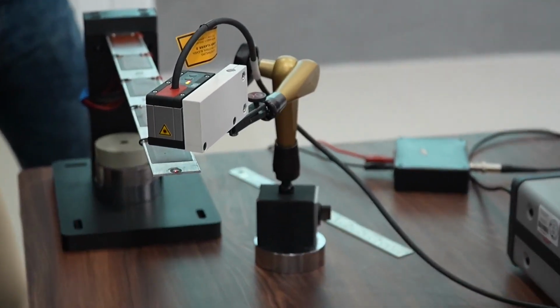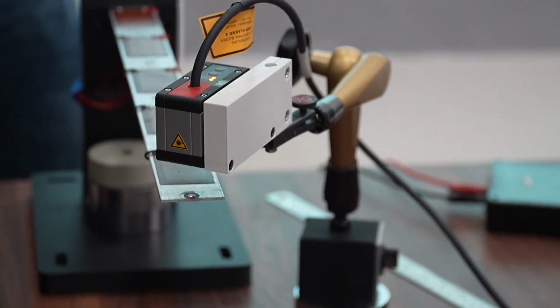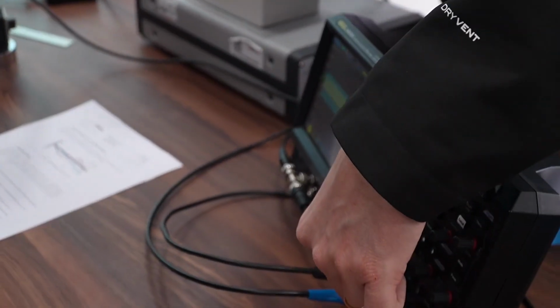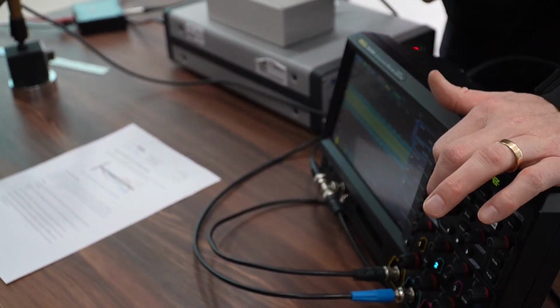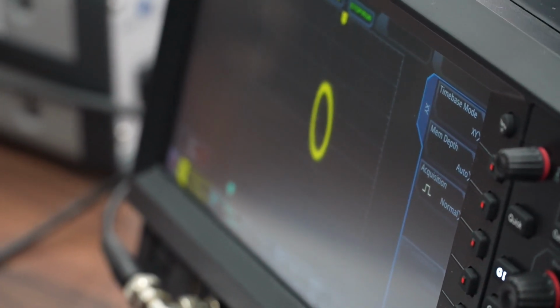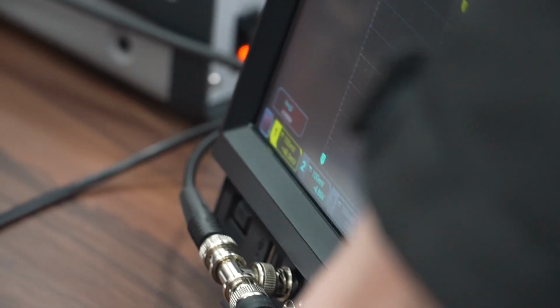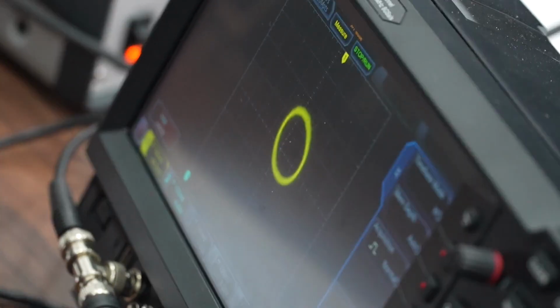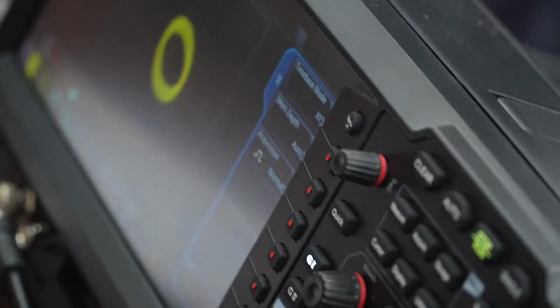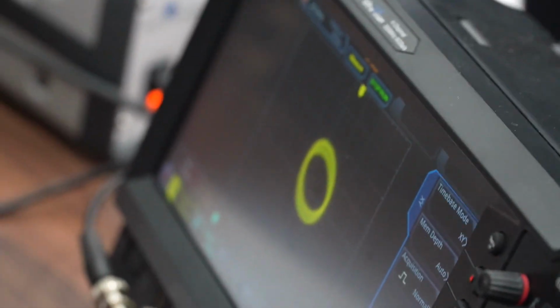So can we put that up a little bit? Up a little bit. Up a little bit. Okay, something like here. Okay, and if we now go again to the XY plot, let's see. It's not a perfect circle because we can zoom in here, but it doesn't have a slope like this or like this. So now you're pretty much in the eigenfrequency. I don't think you will get it much better since the amplitude is really small.